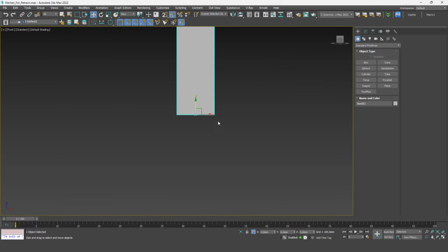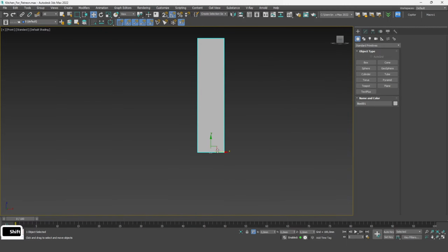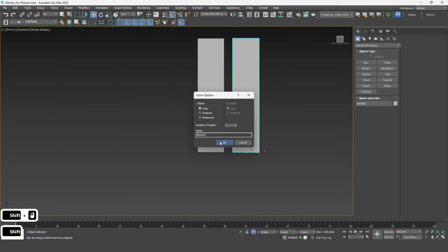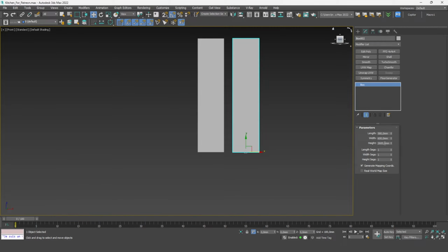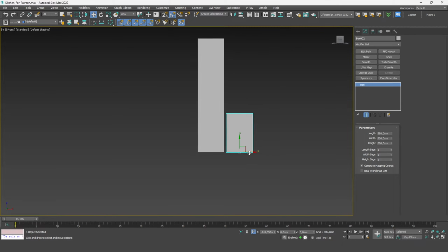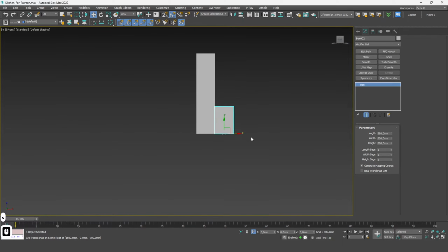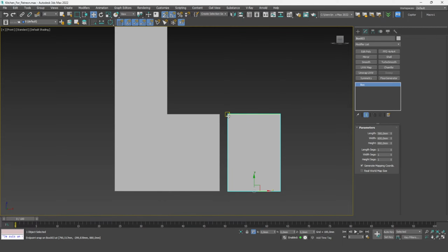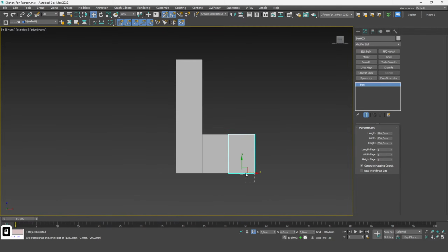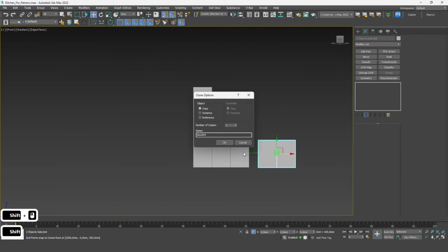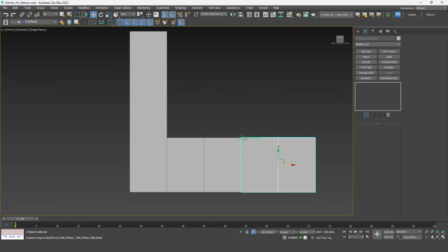We continue, copy the box, and hold down Ctrl+Shift, and select the box height of 880 mm. This is without a countertop. Copy the next box. Do the same with two more boxes. Thus, we assemble the necessary cabinets in modules.